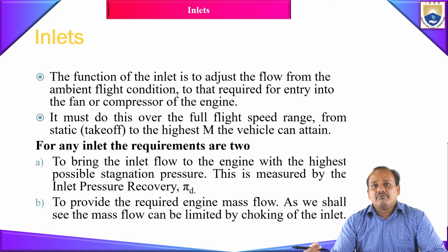So the basic or foremost requirement of an intake is that first it has to supply a sufficient amount of mass flow rate with the least amount of loss in the total pressure, or stagnation pressure. In aerodynamics, in any process you take, there is always going to be an increase in entropy, meaning a loss is going to happen, right?